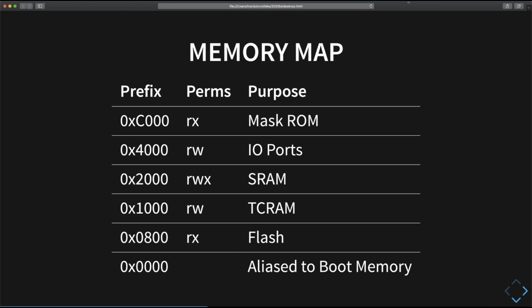If you're so unlucky that you do not have documentation for this, or it's not in the datasheets, you'll find it in the linking scripts. And if you don't have the linking scripts freely available from the manufacturer, you can very often find them included with commercial C compilers. And since you're not trying to use the compiler, you're just trying to read its header files, it's very often not restricted by the compiler's license enforcement.